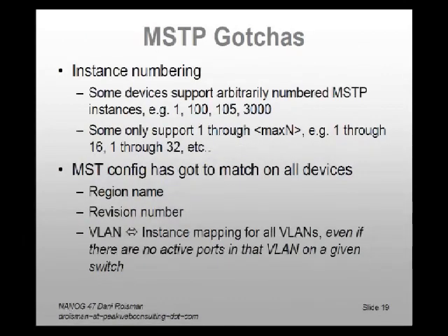Some gotchas that we found, as I mentioned before: some devices you can arbitrarily number instances. You can have instance 100, instance 700, instance 3000. Some devices only support, if they have 16 instances, numerically valued 1 through 16, or 1 through 32. And of course, the MST does have to match on all devices.